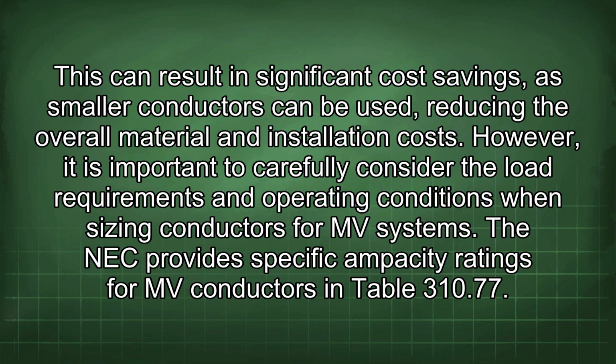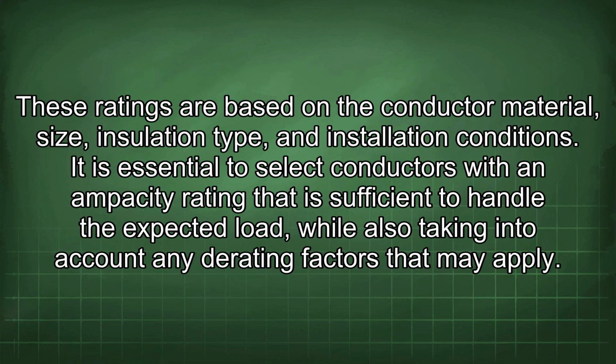The NEC provides specific ampacity ratings for MV conductors in Table 310.77. These ratings are based on the conductor material, size, insulation type, and installation conditions. It is essential to select conductors with an ampacity rating that is sufficient to handle the expected load, while also taking into account any derating factors that may apply.